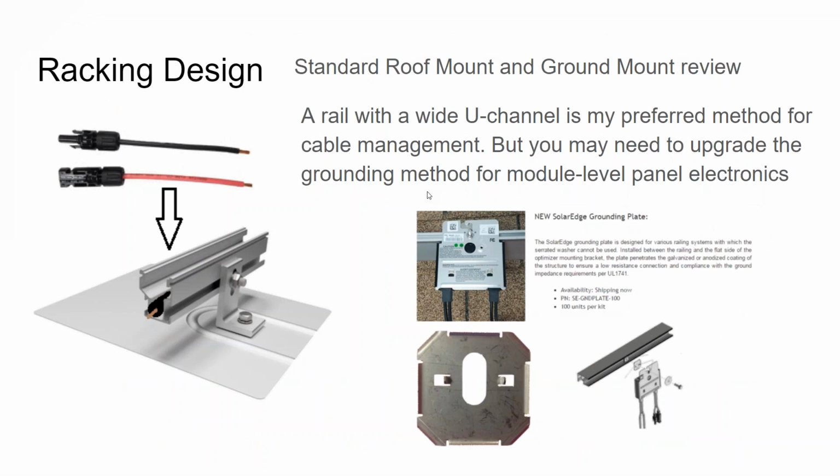And there's smaller stuff that maybe you would only pick up in the field, but the nuances from racking company A to racking company B are in the cable management. With some cable management systems, the cable goes along the side channel of the rail and then gets tie wrapped to the rail, and I don't think that's very elegant. I like racking systems that have this open U channel for the conductors to go into, which gives them more protection against squirrels and critters without actually installing a squirrel guard or a critter guard.